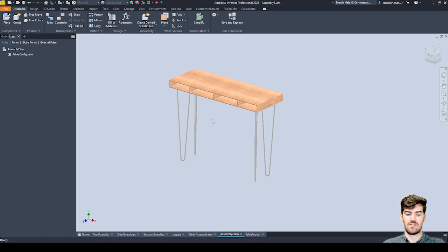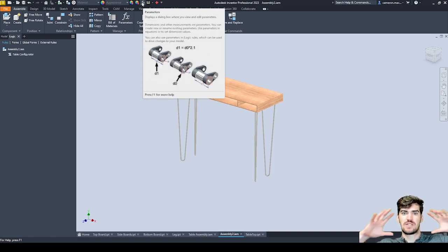What we also want to make sure, which will make this a lot easier going forward, is that inside of our assembly we've got the same values that we want to be driving for those. Say we want a height, a width, a depth, a leg height, and perhaps we want to change the properties of certain components, like the appearance or material of an item. We can add those in as custom parameters, so inside of our assembly we can create those that push the same value down to the children, the parts inside there.